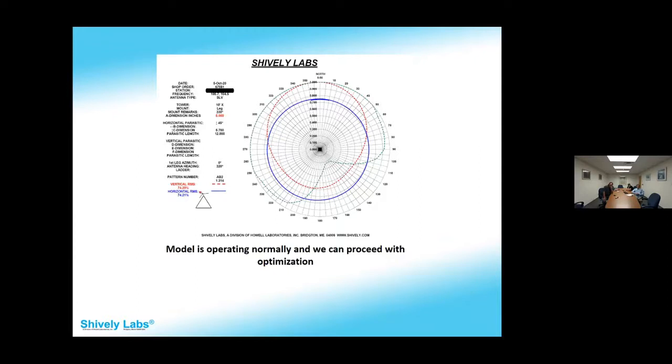You cannot put an antenna on a tower through optimization and have more than, I think, 3 dB of gain. This was discussed at length regarding a situation in a certain part of the country where a non-directional antenna was mounted to the face of a tower, and it had almost 3 dB of gain or more. Actually, it was 2 or 3 for power gain, so more in dB.